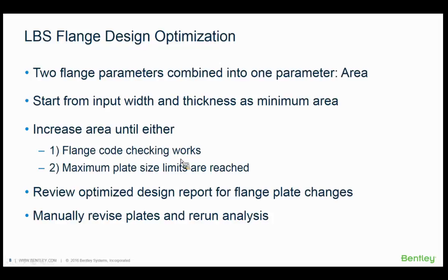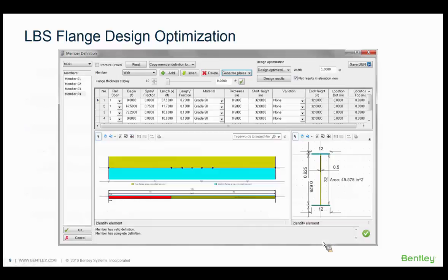Either the flange code checking works or we max out on a maximum plate size. And then we'll take a look at those optimized design reports for those changes. And like I said, you'll need to manually revise those and potentially rerun the analysis again.